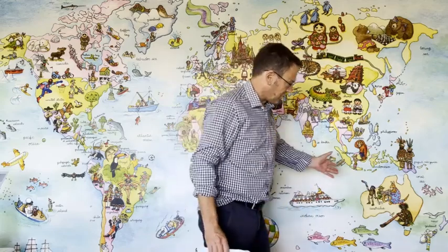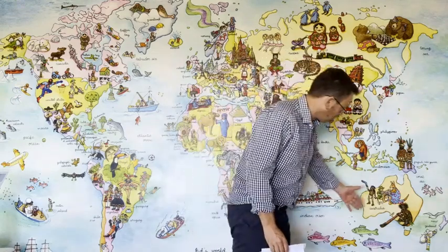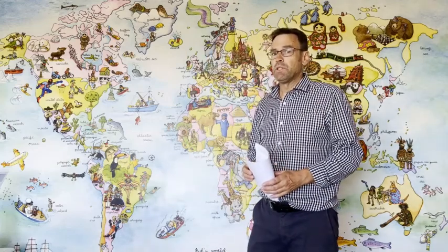Now, for a country the size of Australia, if you tried to do one projection to cover the whole country, you would end up with massive distortions out either side, which would trip you up in most applications. However, if you're a smaller country, you've got the luxury of potentially moving away from the UTM zone projection and adopting your own. And that's exactly what happens in many parts of the world.